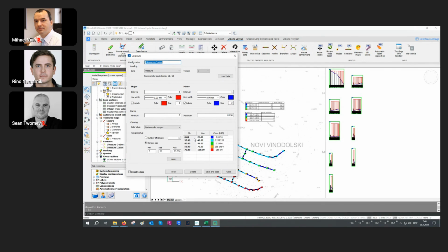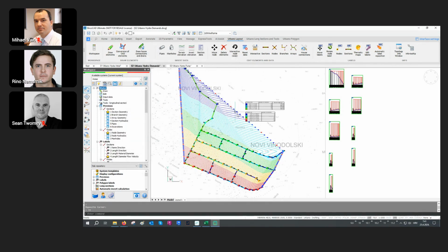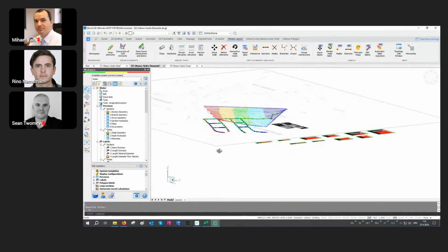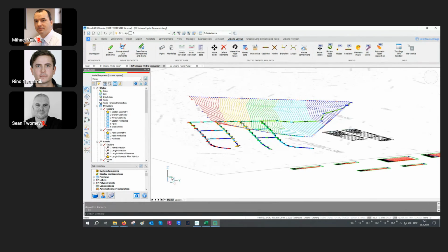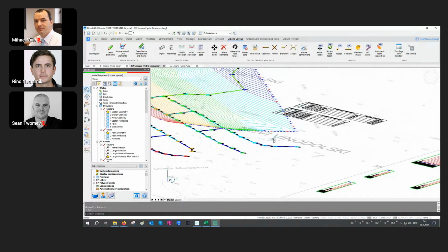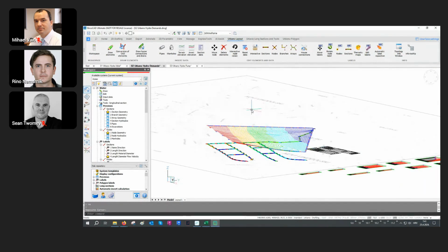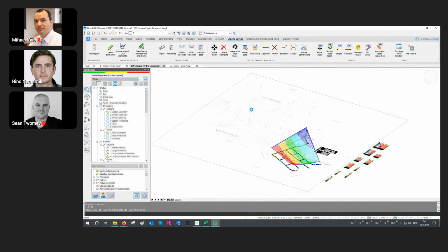You can define the ranges and also the colors, but I like to use the default ones, because if you're using the default ones, then the colors and the ranges will match those legends that we already have from the thematic maps. So now when we click draw and save this, we have these contours showing us different ranges of the pressures. We can also go to 3D view and check these different zones of pressures. Okay, let's go back to plan view.